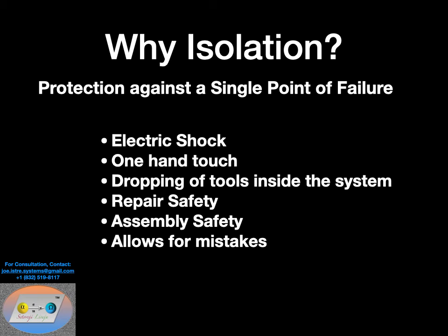Obviously, if you put one of your hands on a terminal that's at, say, 1,000 volts and the other one that's at 500, you still got a shock hazard across your heart that could do very bad things to you. However, if you're only touching any part of the system with one hand and your feet are touching the ground, then there's no danger if your system has isolation from ground. See where I'm going?